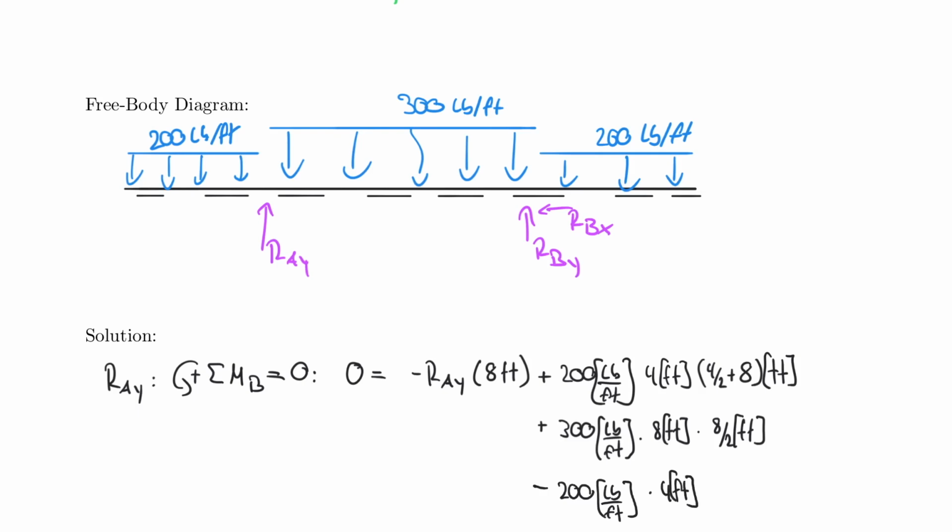But now the distance is from its lumped force to the support, which of course is half the distance it's acting over. So we would look at 4 over 2 feet. And that is the entire equation. This is the only educational part we have to go through in this example so that you understand which part of the distributed force rotates about which point.